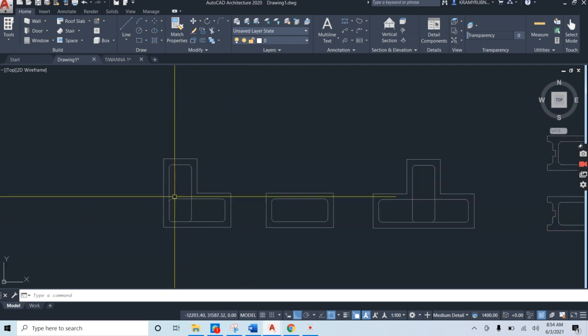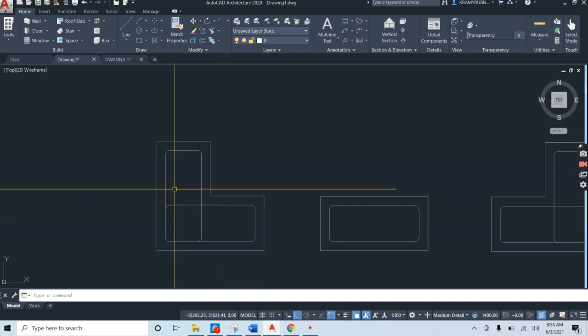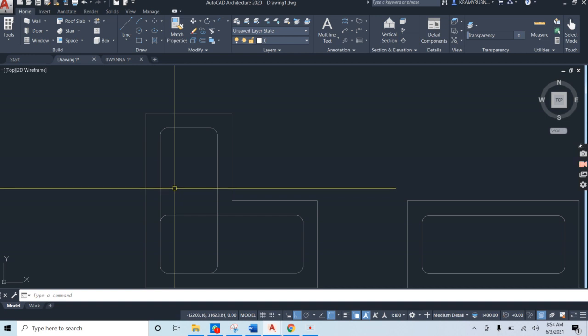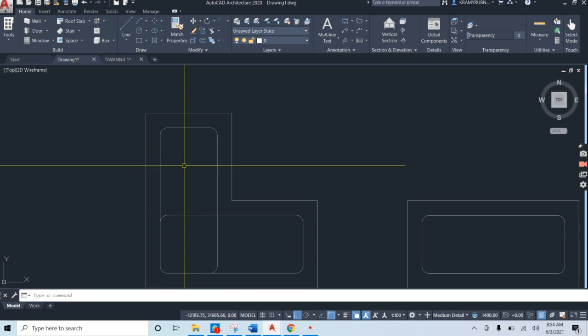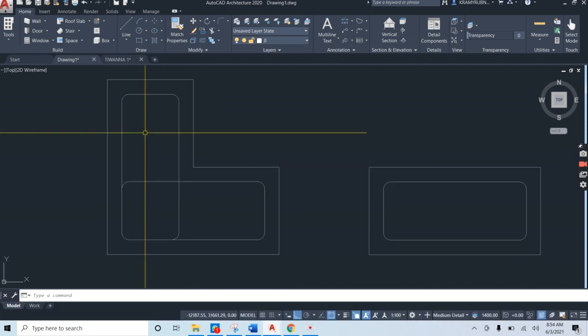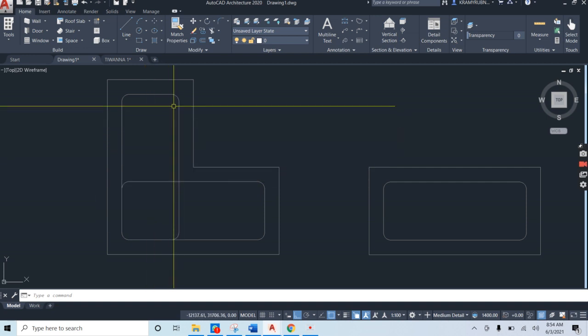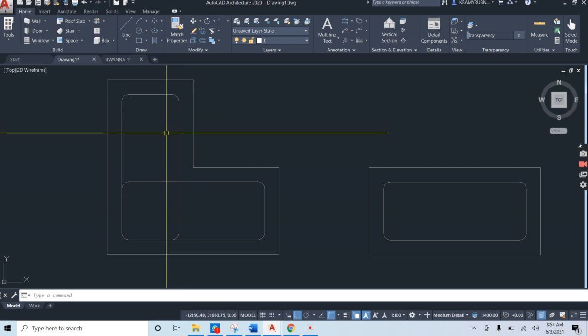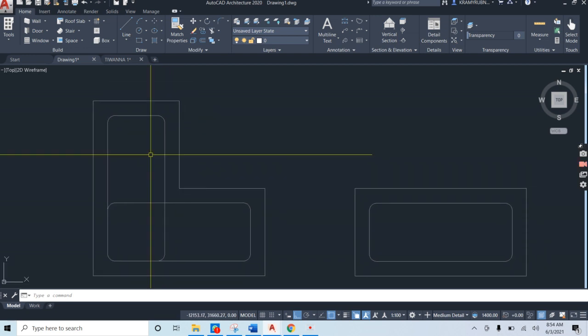Yes. Now what is missing in our stirrups, in our stiffeners? Our vertical bars are still missing. Now, how do we know where in a stiffener a vertical bar is to be placed? Vertical bars are placed pretty much wherever there is a curve. Now, what size vertical bars are we going to be using in the construction of our wall? We're going to be using the typical 1/2 inch rebars.